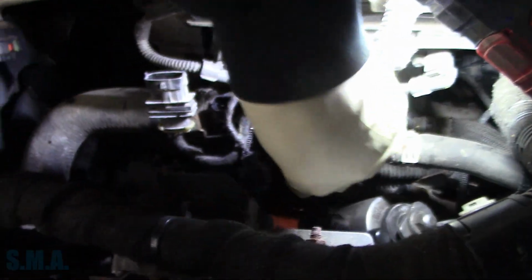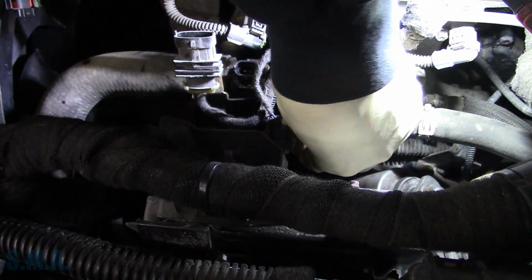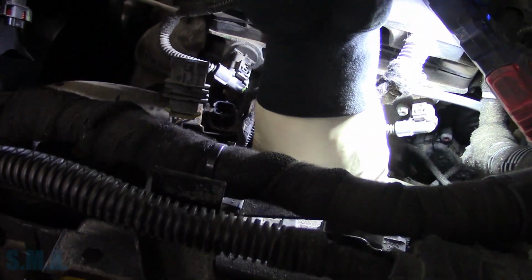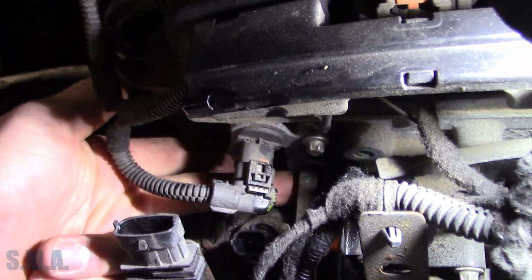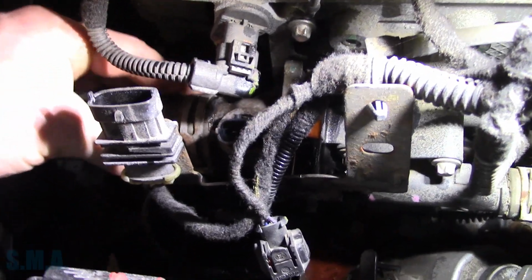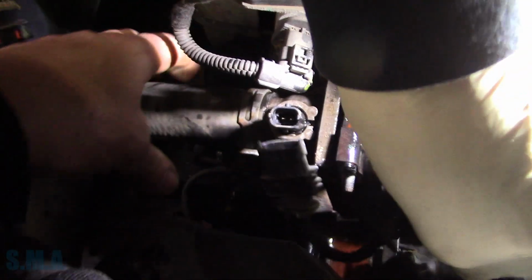So it looks like this bracket has to be removed, Jay. Oh, gotcha. Okay. Is that 10 millimeter? Oh, probably. So I gotta pull this bracket off. The thermostat housing was hitting, what was it hitting? Just where the air pump bolts onto the block right here, the thermostat housing comes out and hits it. I don't know if that's gonna help you or not.